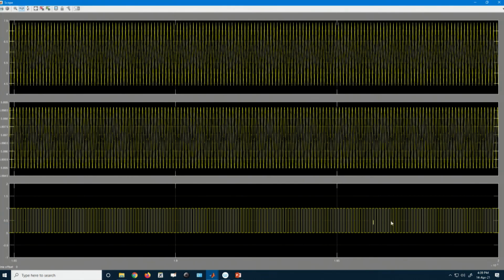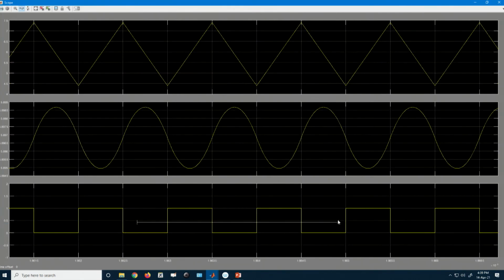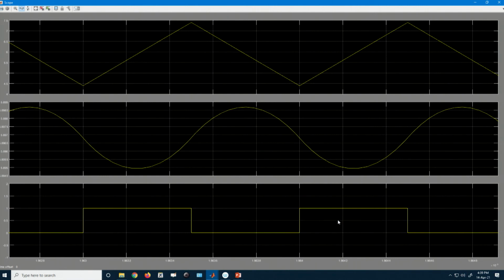Okay. So, now if we want to see the voltage profile, it looks like the perfect capacitor voltage that we have discussed. That means, whenever the inductor current reaches its average value, from that point the capacitor starts charging. Whenever it again falls below the average value, then the capacitor voltage starts falling. So, that is very consistent, because the capacitor current is positive when the inductor current is above the average value, which is the load current for this case, and negative below it.